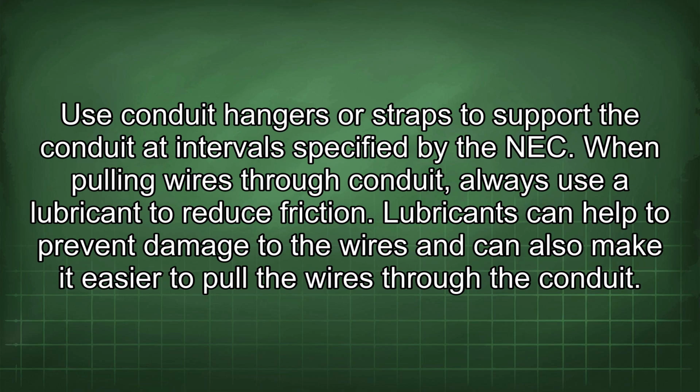When pulling wires through conduit, always use a lubricant to reduce friction. Lubricants can help to prevent damage to the wires and can also make it easier to pull the wires through the conduit.